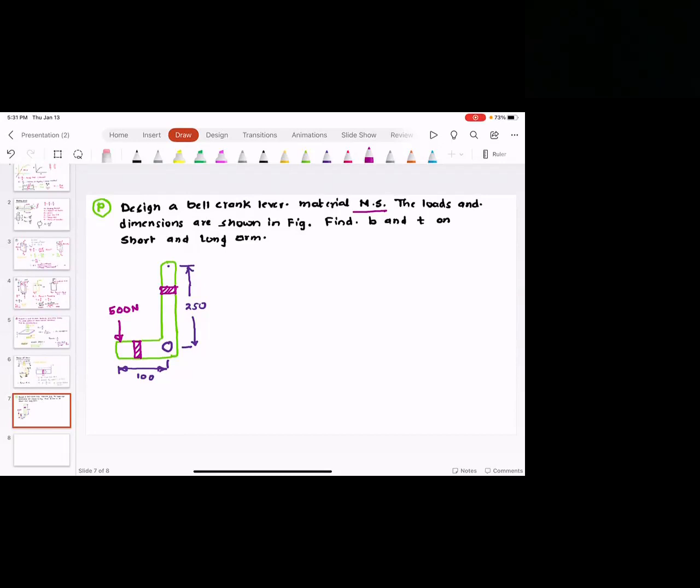But as a rule of thumb, the yield stress, which is the stress at which the steel starts losing its elasticity and you transition from elastic region to plastic region, is about 300 to 350 Newton per millimeter square. Assuming the factor of safety of 3 to 4, you get to the range of about 70 to 75 Newton per millimeter square.